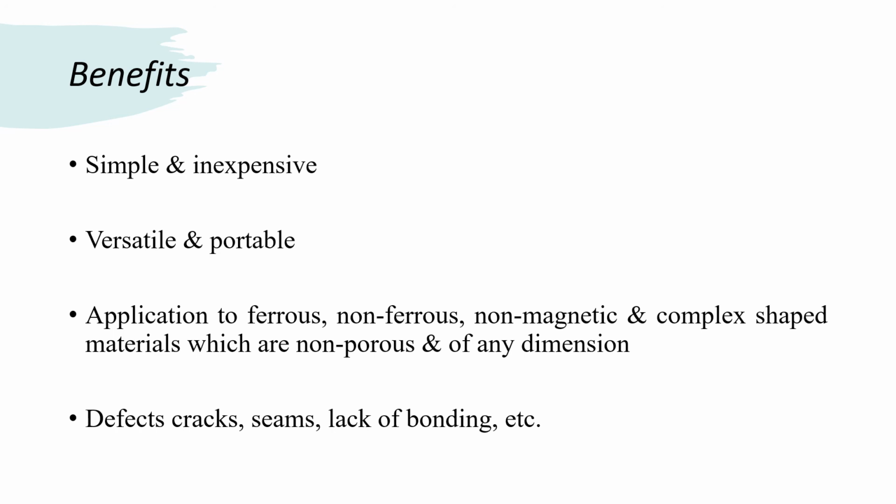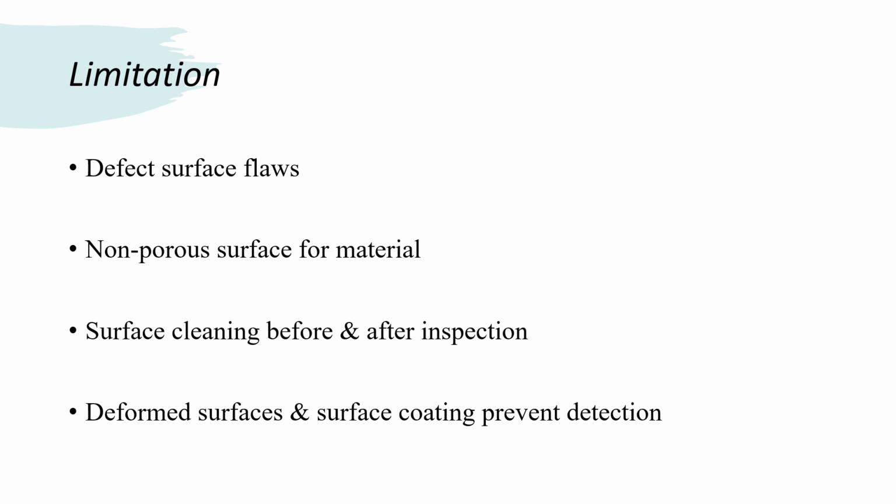And what are the limitations? The limitations in this method of testing are that it detects only surface flaws, needs a non-porous surface of material, requires surface cleaning before and after inspection, and deformed surfaces and surface coating prevent detecting. So these are the limitations.